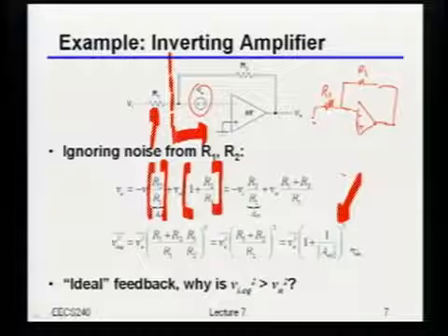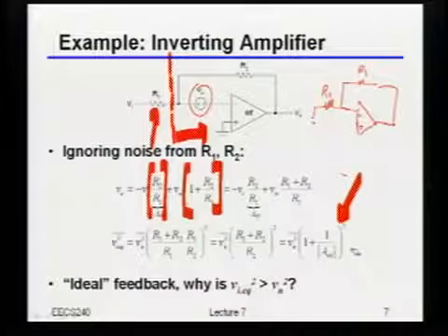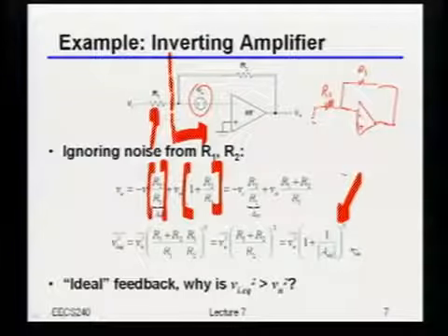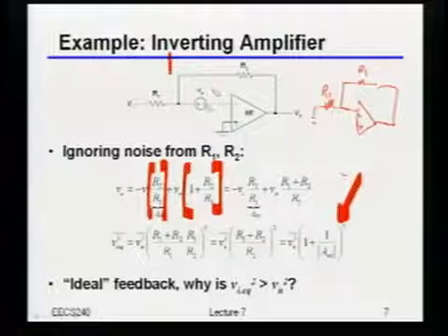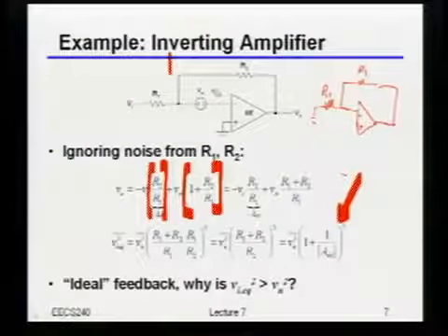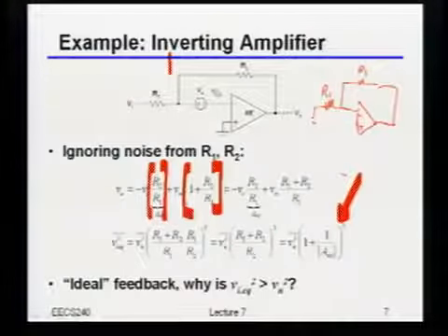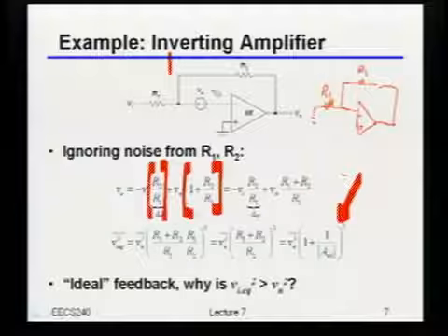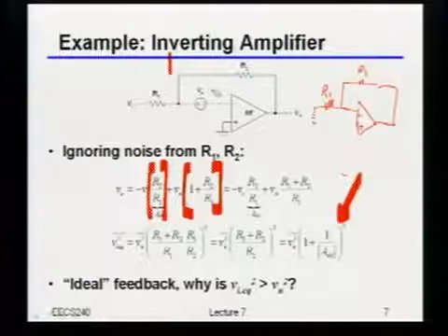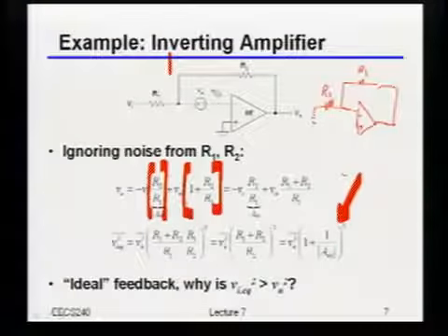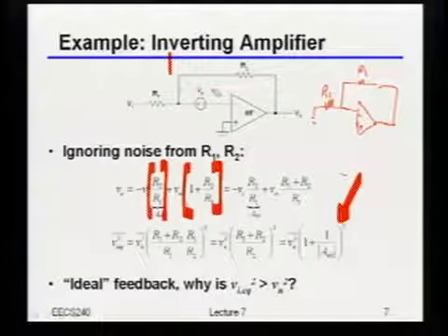So just in case you were wondering why we went through all that stuff about source impedance, this is a really good example. Because it's kind of innocuous, right? You'd think that maybe I can make the resistors big enough that they're not that big of a deal, they're not going to cause any problem. Well, guess what? It doesn't actually matter what you had chosen there. Even if they were perfect resistors, you'd still mess up the noise performance, simply because you changed the source impedance. Does this make sense to everybody?